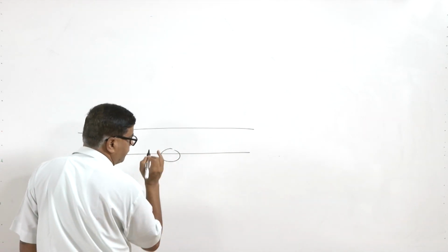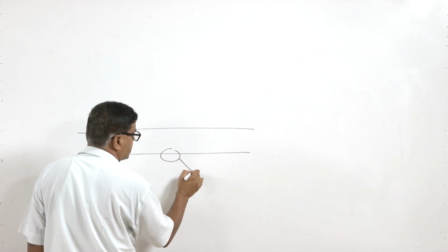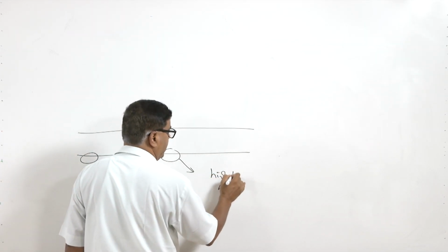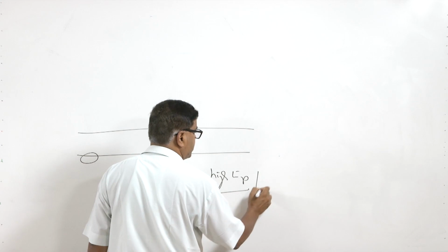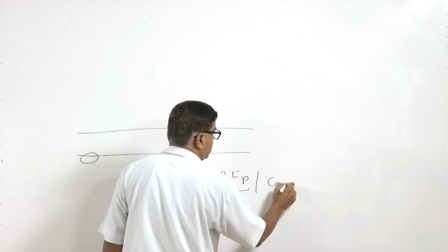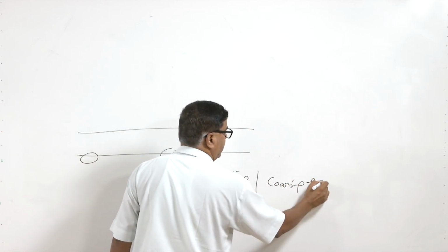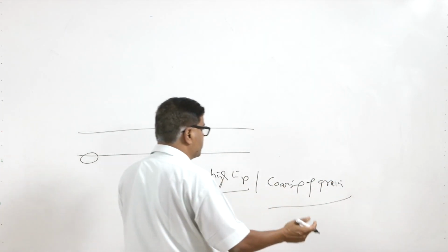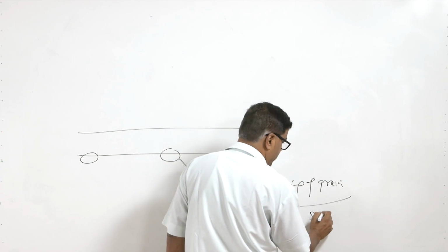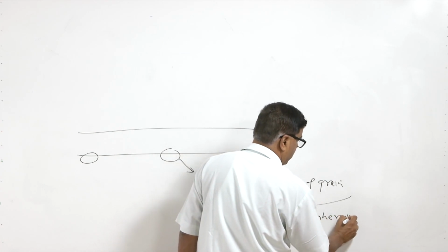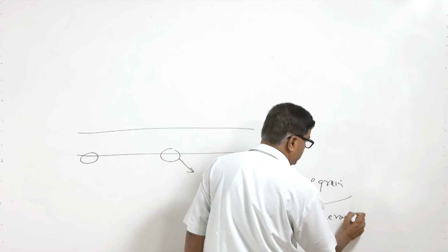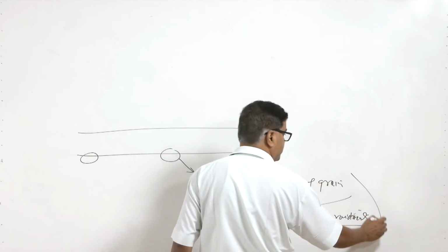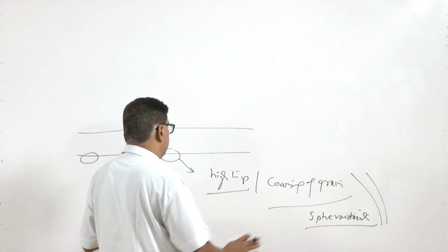If the failure has taken place from this location, then a sample from this location will indicate that at high temperature this zone has been subjected to coarsening of the grains. Excessive coarsening and prolonged high temperature exposure can also lead to spheroidization of the steel component. This is a problem especially observed in boilers.